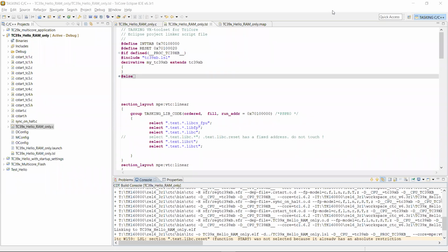That's one thing. Another thing is that the flash components on the chip only have a limited amount of read and write cycles. So you can only program the flash for a finite amount of programming operations. So you can do this 100,000 times or something like this, and then you see that the flash will degrade.